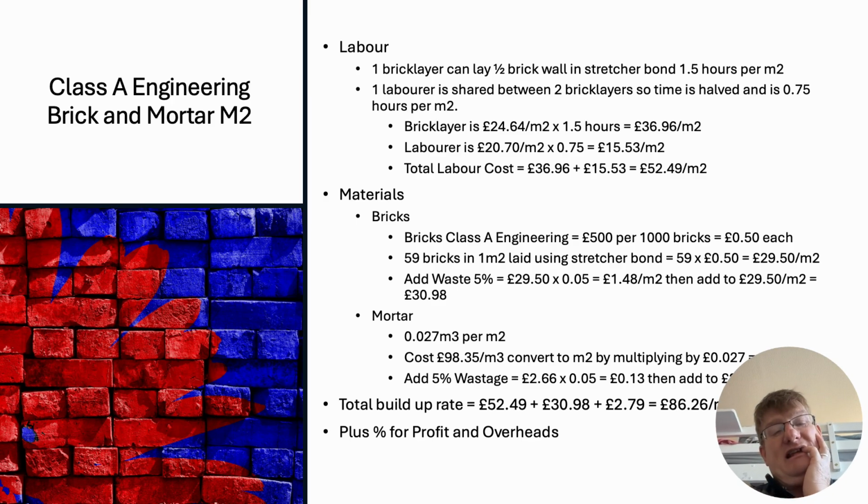Class A. So Class A would be substructure. But can I just say, fundamentally it would be the same, same with any bricks, really. You'd just look at those slightly different figures, with regards to maybe the mortar that you're using, because the mortar that you'd use below ground, below DPC, would be much stronger, would have a higher compressive strength, and it would probably be just sand and cement rather than any lime or colour added to it, because that will weaken it.